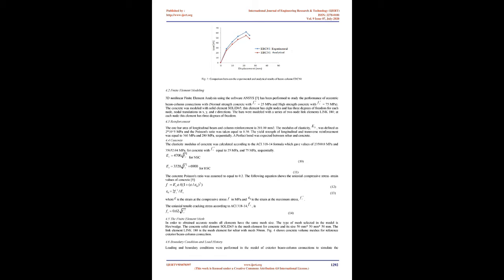4. Finite element analysis. 4.1 Validation of the model. With the comparison of the experimental program and analytical results, the validation of the current model has achieved a range of 91 to 93%, as shown in Fig 3. This disparity in results is due to the effect of the boundary conditions and assuming full bond between reinforcement and concrete. 4.2 Finite element modeling.